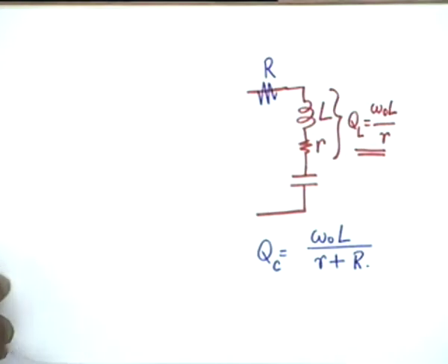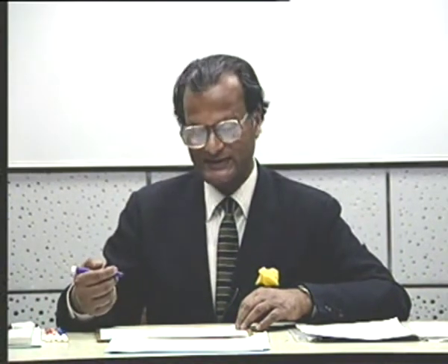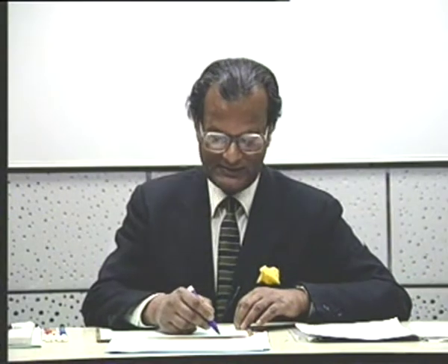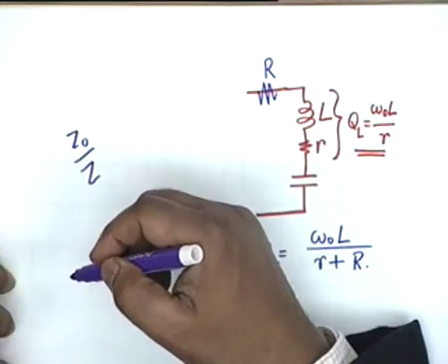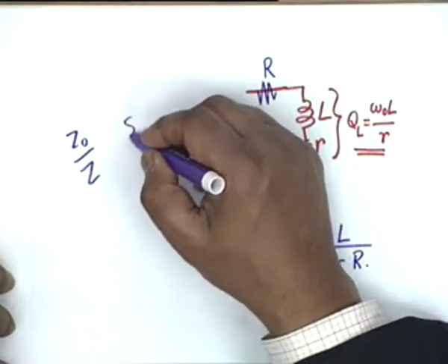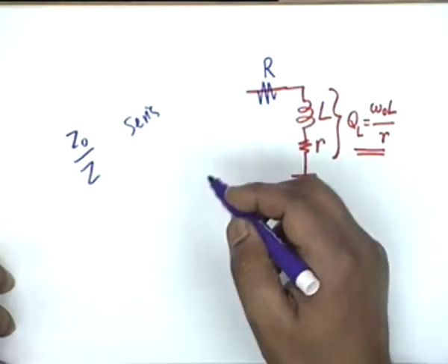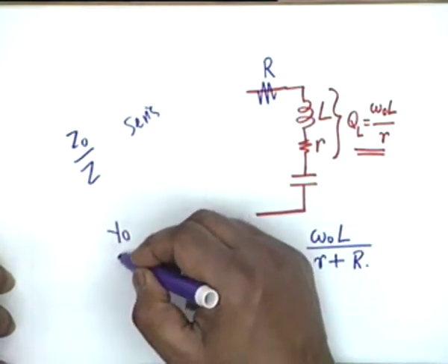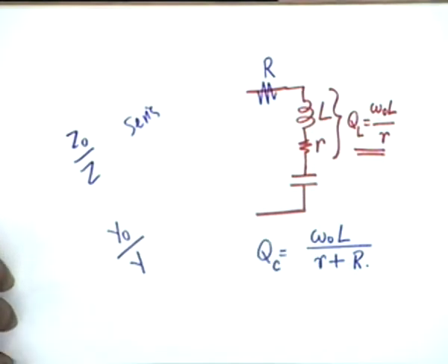All right? Yes. Formulas for impedance and all that you gave in terms of Q, are these valid for any circuit? Any circuit consisting of R, L and C, parallel as well as series. In the parallel case, you will have to take the admittance. What did we take here? Z0 by Z, isn't that what we took, in the case of series resonance. In the case of parallel resonance, we shall have to take Y0 divided by Y.